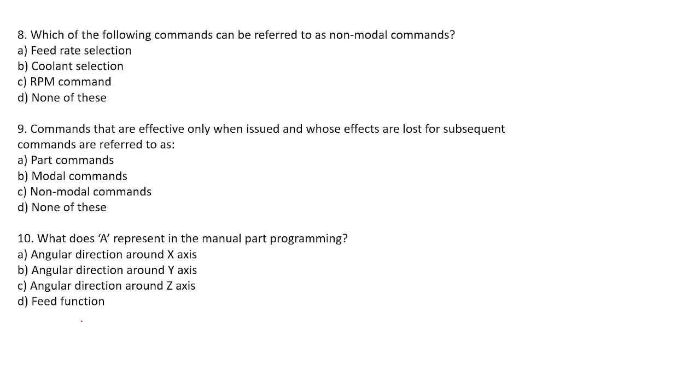Adding to that, feed rate selection, coolant, RPM, those are written at the beginning of the program, and throughout that program they are fixed. At the start of the programming, you will fix those parameters, speed selection, coolant or RPM. So those are fixed throughout your program.